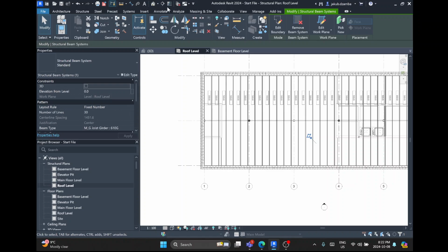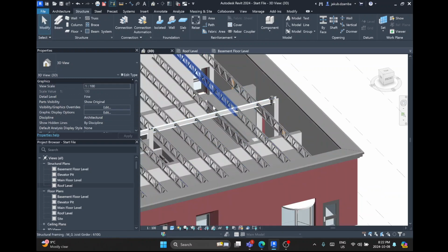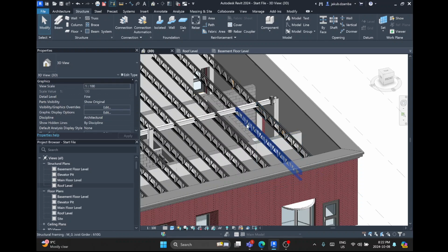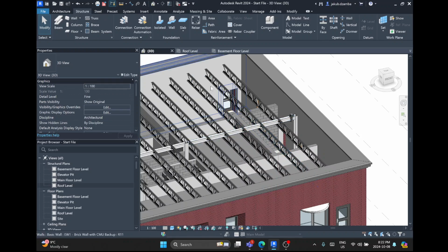Now, one thing that might come into question here is, okay, what do you do with these stairs that are technically fire exits? And you need a 2-hour fire separation. Well, we could add a fireproof ceiling in here that would maintain the enclosure, but a legitimate issue could be brought up, which is that the structure of the ceiling is held up by beams, joists, that are also spanning, so even if you fireproof them in here, they're still connecting structurally to the parts where they're perhaps not fireproofed. And so if you have a fire out here, this steel gets chewy, breaks down, and by this breaking down, it also destroys this roof and defeats the purpose of that fire enclosure.